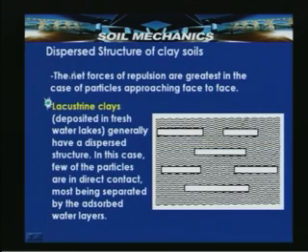So, let us look into these two structures which we defined from the influence of the particle forces and their behavior. One, we said, is the dispersed structure. In the dispersed structure of clay soils, the net forces of repulsion are greatest when particles approach face to face. The particles can come face to face in the soil water, as shown here. Because of the low ion concentration and thick adsorbed water layer, the net force will be repulsion.